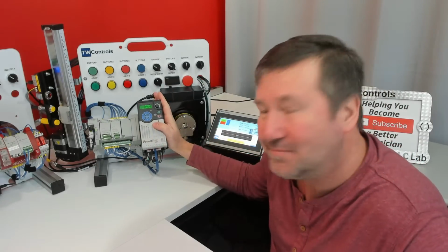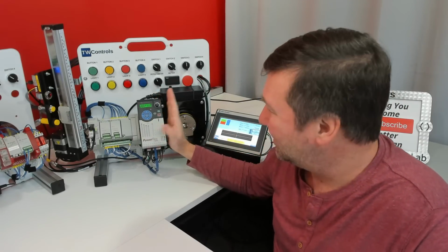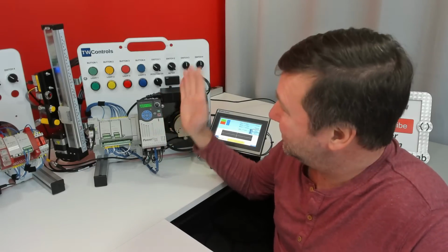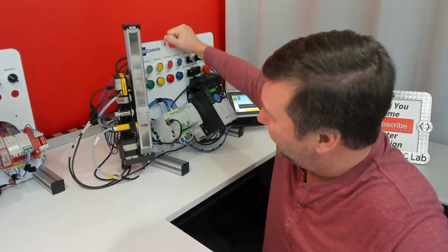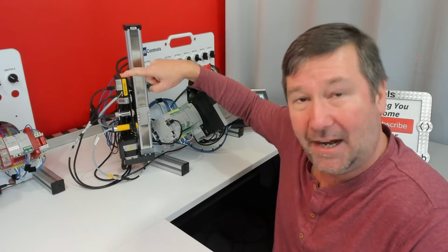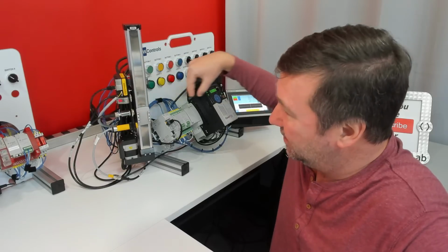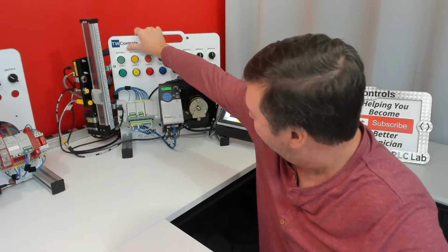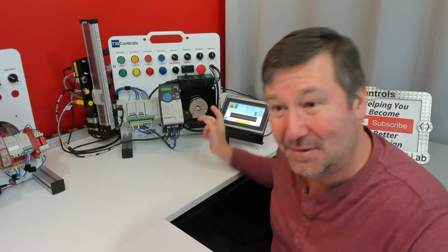And then we started adding drives and things to save some panel wiring and give us a little more diagnostics. And now, this linear actuator is operated off of Ethernet. We have IO-Link over here that's giving us actual distance information and various sensors, picking up this encoder.